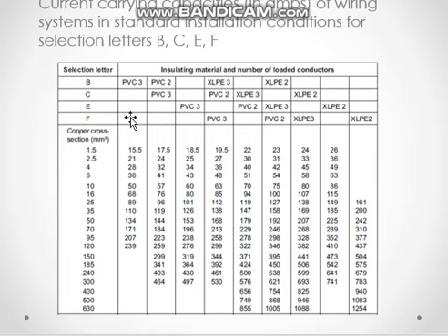For example, you have calculated your current, then you get in single phase 51. If you have got 51, you have to consider this 57 as it is greater than the 51 you have found. Don't use this 41, as this 41 is not capable of carrying that 51 current.